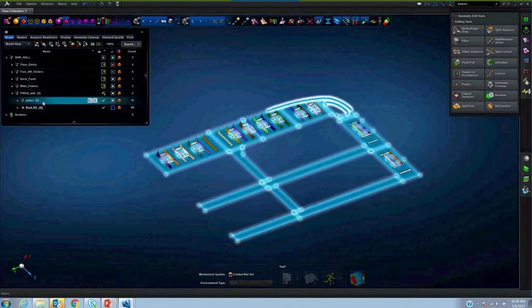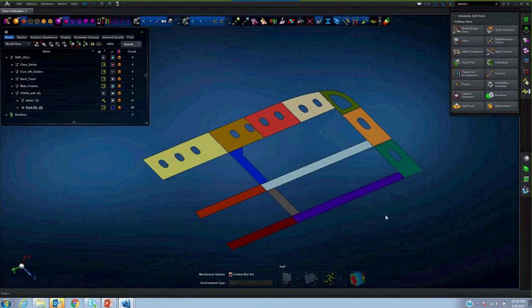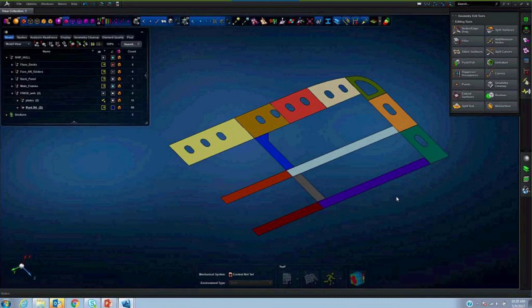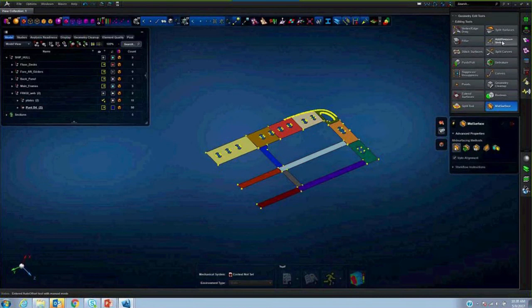All right, so here are the 2 parts here. And now, because of these parts having a various thickness, and because we created mid-surface geometry, all these plates are not necessarily aligned in a plane. And so when we need to extend all of them, we need to bring them into a single plane, and that can be done using this tool, what is called auto up to alignment. And before that, let's get rid of some of these extra vertices in the model. That is done.